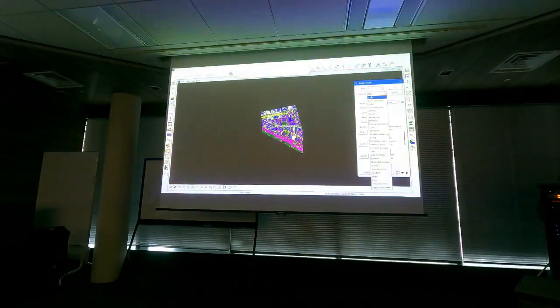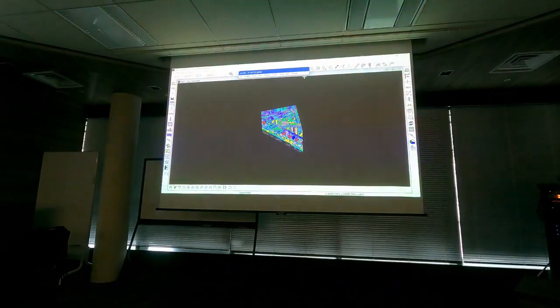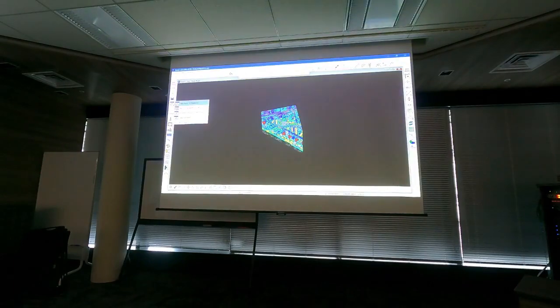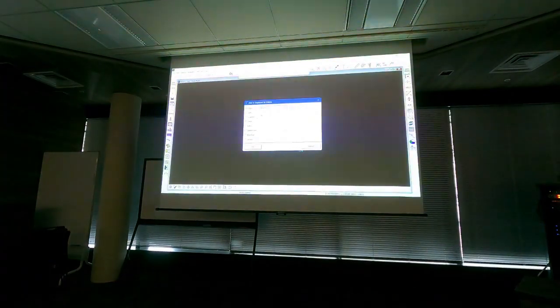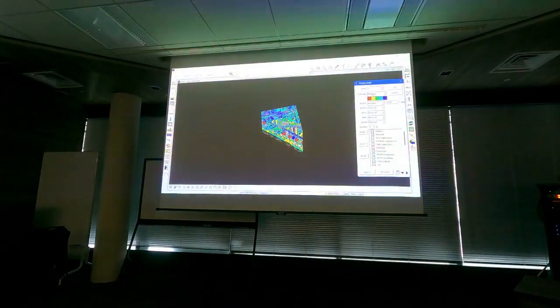First check that I have distance computed. Yes. And with the distance computed, I can say add to display set by criteria, and perhaps say that it is points which are half a meter to 1 meter above ground. And now I can say that my universe 1 should display set only.